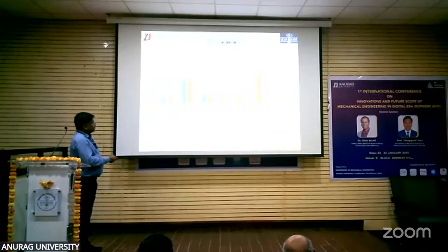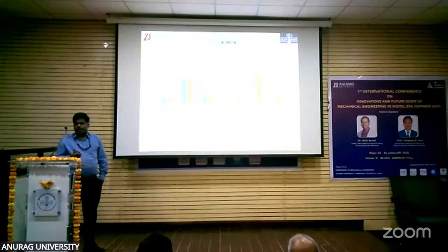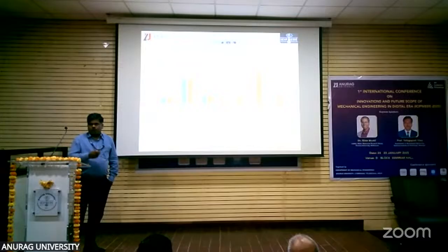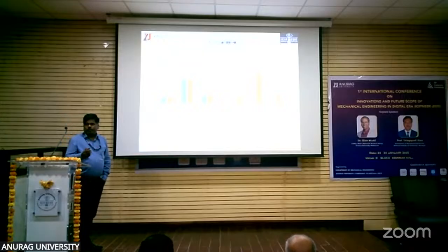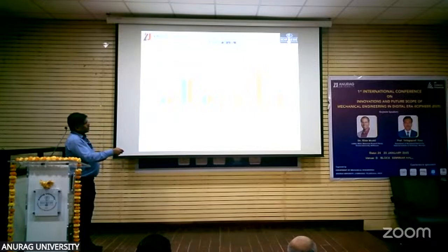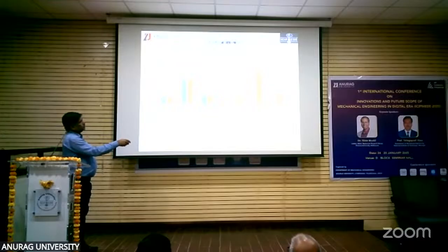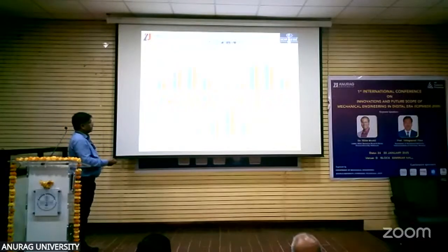And the heat duty values, and what is the heat duty taken by the economizer, evaporator, superheater, reheater. We know that at low wattage power, few boilers will have a reheater, so these two will not have the reheater facility. But here, I compared economizer, evaporator, superheater. So this is the comparison between the Python tool evaluation and the real-time operating point.